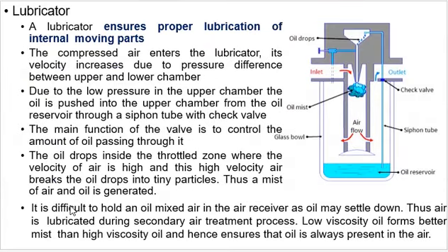Then we move towards another component, the lubricator. The lubricator is a device to ensure the proper lubrication of internal moving parts. The lubricator works on the venturimeter principle. If you remember, you have studied the venturimeter in second year in fluid mechanics. So the inlet is there, the outlet is there.